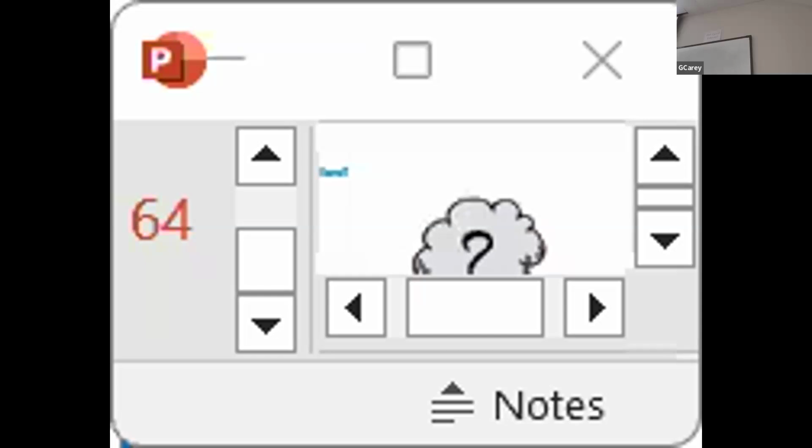I mean, it took away some of those concerns that they had with the high pressure drop across the control valve. It did that, but you were consuming a lot of energy. And again, this would just be a more modern drawing of the exact same thing, three-way valves. But eventually, obviously VFDs showed up and all of that. This is just showing a three-way valve.